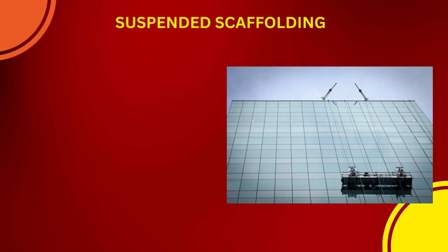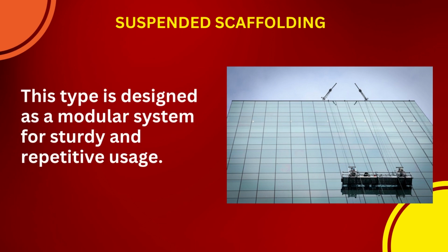The next is suspended scaffold. Suspended scaffold in its true meaning is not a scaffold, rather a facility to work in a hanging or suspended position, just like for cleaning of the glass panes of a high-rise building. So it is suspended from the top with the help of cranes basically. So it is designed as a modular system for sturdy and repetitive uses.